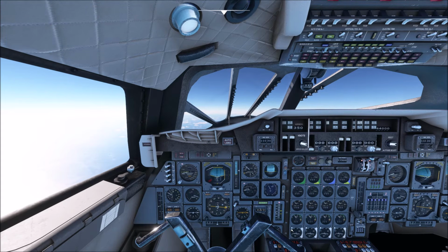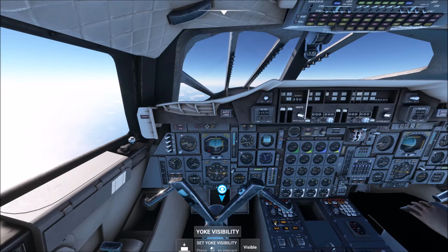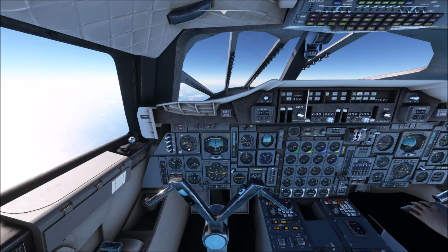Burners out there, I think, at the moment. Yeah, definitely burners out. It's not needing them at the moment as much. Reduce the climb rate, Mach 1.3 just coming up. And again, it's now much further, about 480 there, maximum indicated. That's given us a Mach of 1.3, probably 745 knots ground speed now.